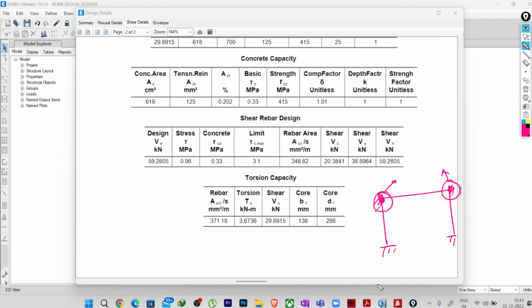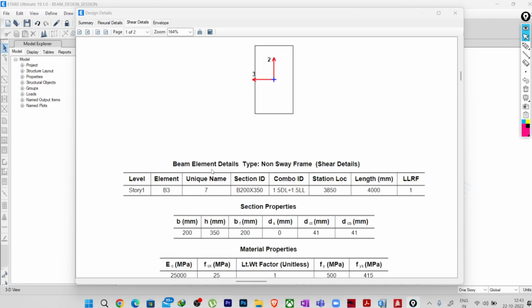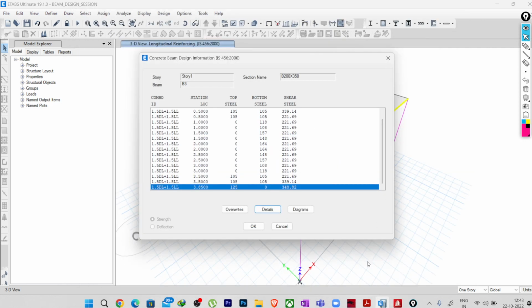So design will be exactly the same. Analysis is changing because of the methods or assumptions that we are making. So the analysis will also match if you do the matrix method and solve it as per your design criteria. Okay, so this is how you can proof check your different softwares by seeing whatever output they are giving. The same thing you can do with STAAD Pro also.